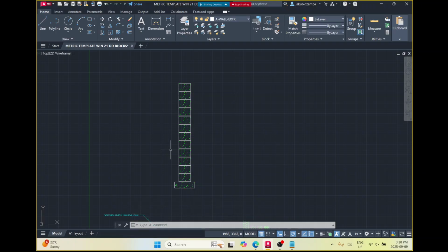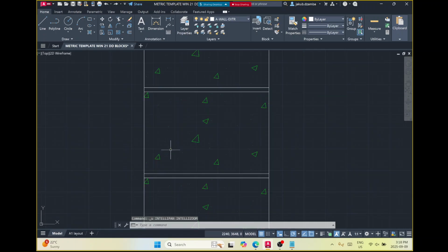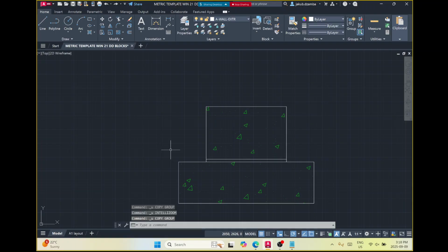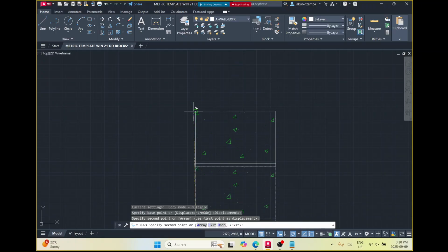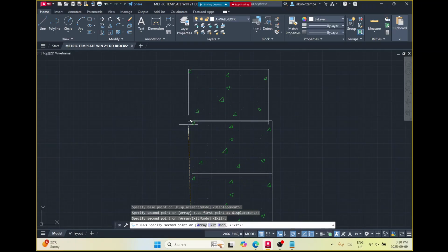I'm gonna do that again. So I'm gonna undo what I did. Back to one brick. So copy. And again, this is all in video, so don't worry. You'll have this uploaded on YouTube to reference it. I'm gonna select all of these pieces. Hit enter. Pick the bottom left corner. 1, 2, 3.